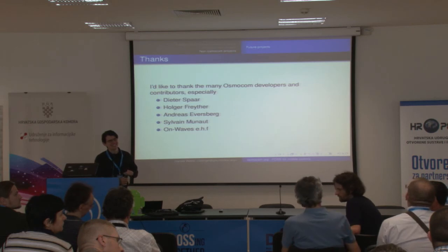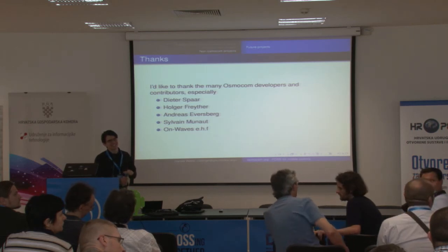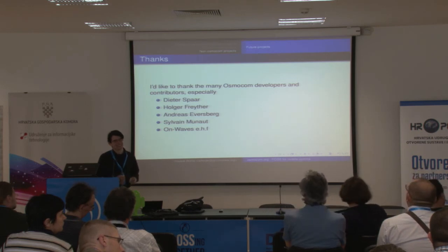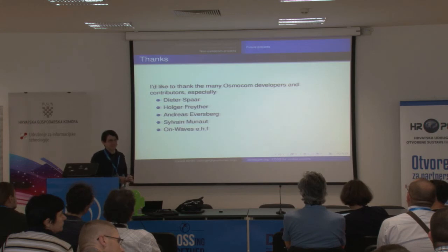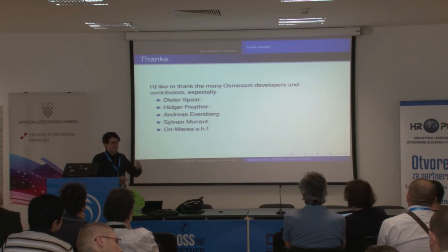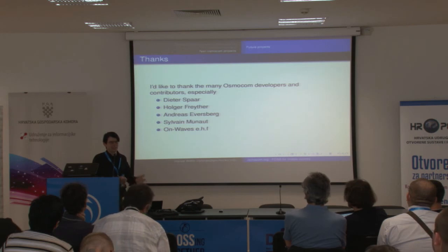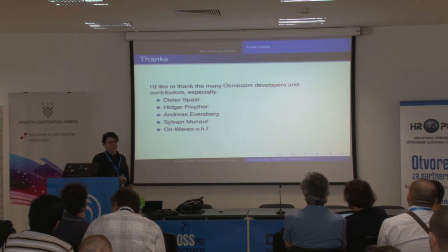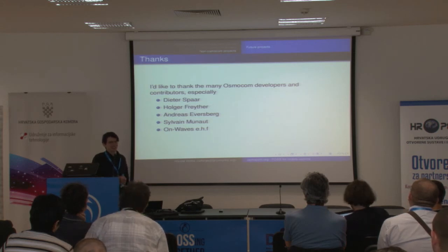Which software-defined radio hardware would you recommend for a start? There is now HackRF and so many options. On the cheap, for example, for students or somebody like that. Yeah, I would just go for the RTL SDR. You can't get cheaper than $20 or so. It's receive only, you cannot transmit. But still, in SDR, there's a lot of theory, a lot of software that you need to get at least some hold on and some understanding and some experience. So I think start with the RTL SDR, and because it's so cheap, you don't need to think about that expense. Once you hit the limits there, then you can think about the next thing to buy, and that changes every year or every 2. You find new hardware that has better properties and so on.